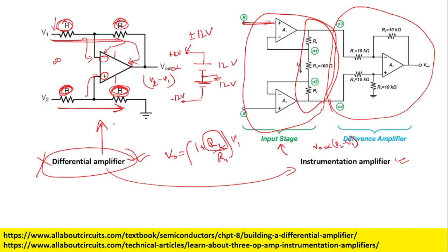So what is the way out? So this is the gain. Suppose I am having, say, R2 is 100 and R1 is 10. Then 1 plus R2 by R1 gives me 11. I can have two of such stages. We discussed cascading of stages.